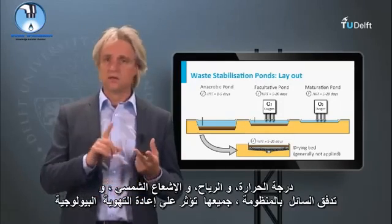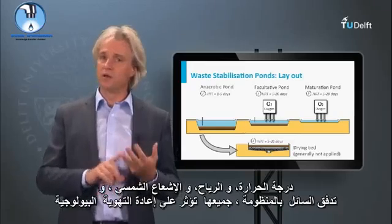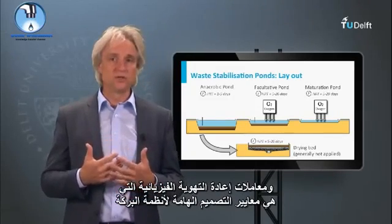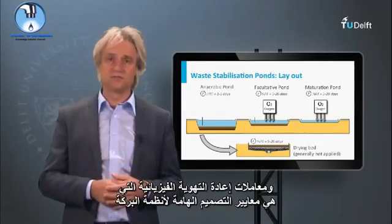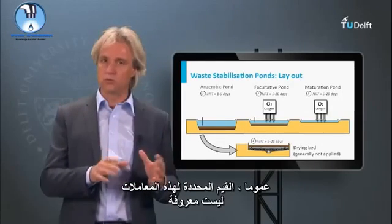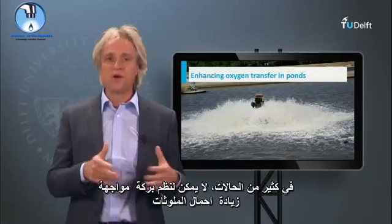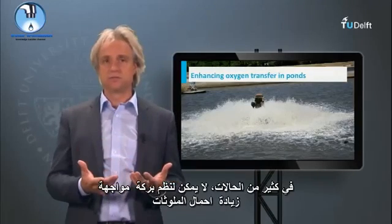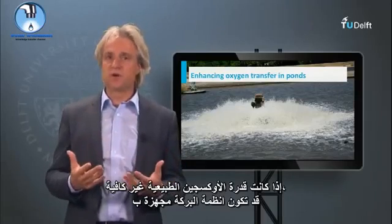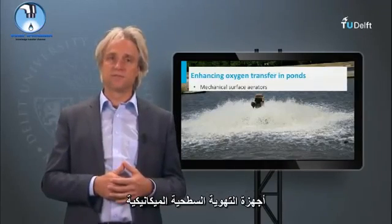Temperature, wind, solar radiation, and liquid flow regime all impact the biological reaeration and physical reaeration coefficients that are important design criteria for pond systems. And generally, exact values of these coefficients are not known. In many cases, pond systems cannot cope with the increasing load of pollutants. If the natural oxygenation capacity is insufficient, such pond systems might be equipped with mechanical surface aerators.